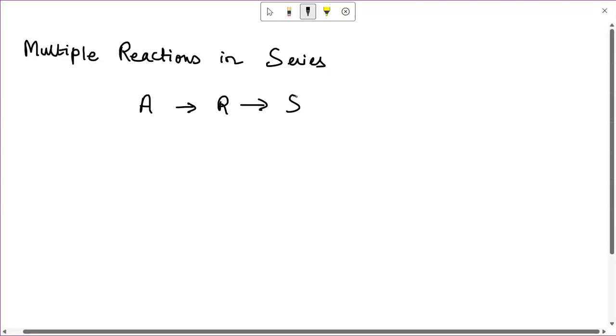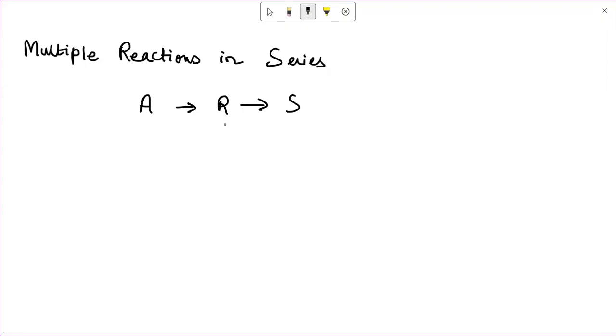Okay, and the maximum possible amount of any of the intermediate, in this case being R, is obtained if the fluids of different compositions, or the reactants at different stages of conversion, are not allowed to mix. Okay, so here we are just going to see reactions in series for the irreversible type, and for different kinds of reactors, what would be the way we quantify the product distribution and the reactor sizing. That is the target over here.